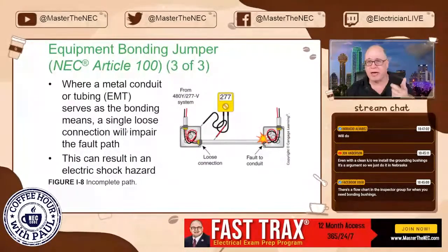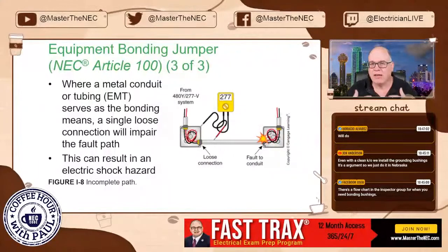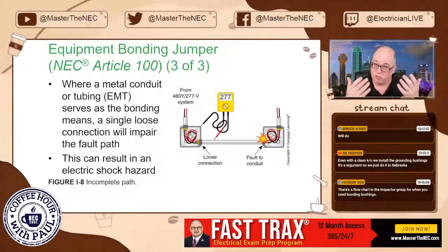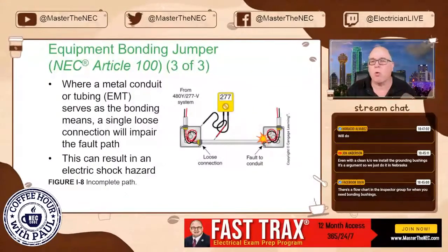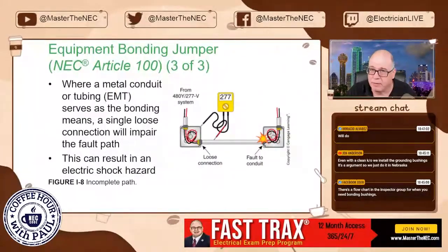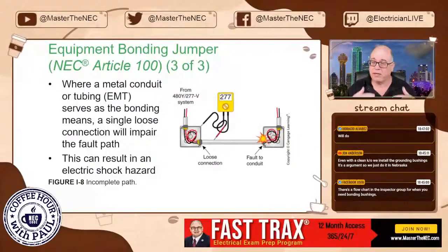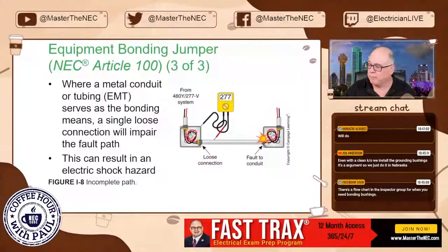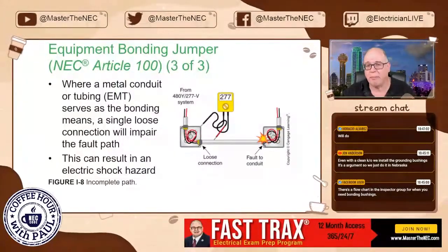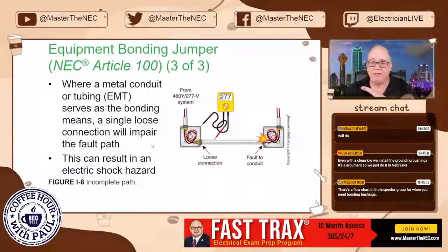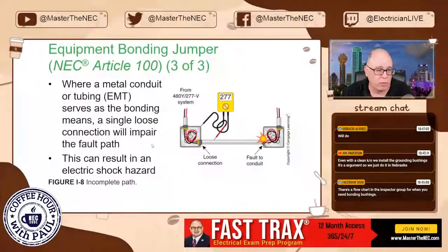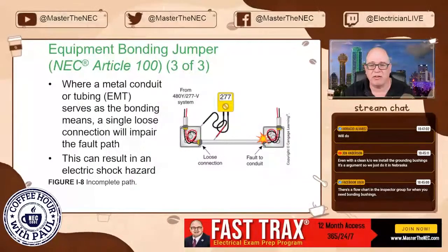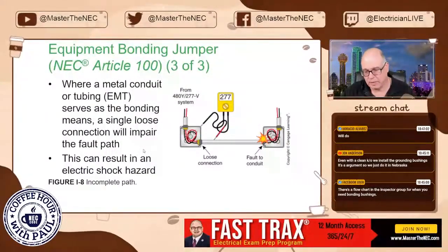In fact, on a rooftop for HVAC, if you're using compression type fittings and things like that, which is outside in a wet location, then you're required to run a wire type equipment ground in there because of vibration and movement. But again, everybody does what they want, but a lot of people, that's the reason why they put the wire type in there. So I don't have anything wrong with using the raceways and things like that. I'm just telling you why a lot of engineers and designers want the equipment ground in there, okay?